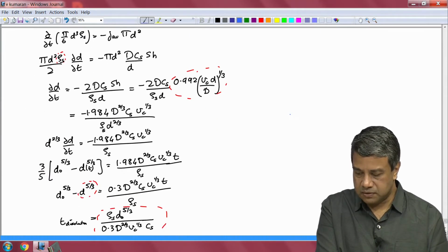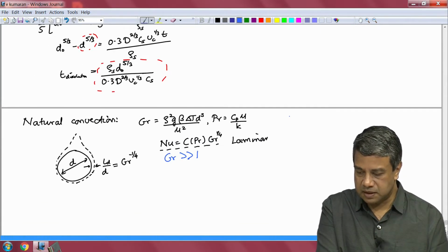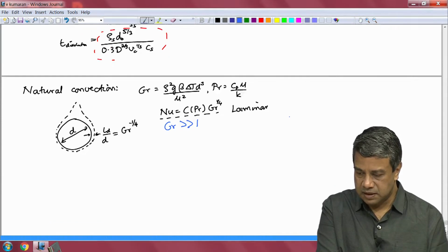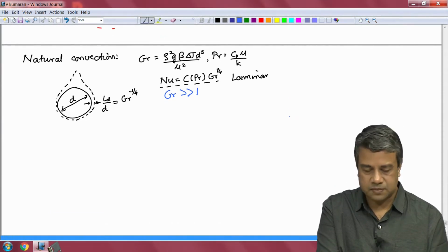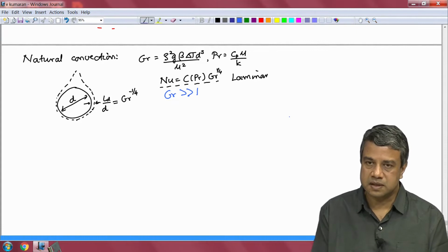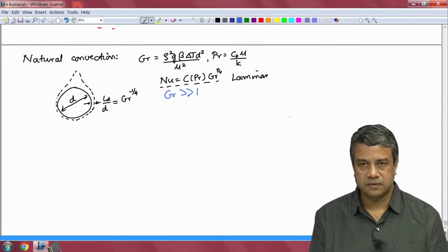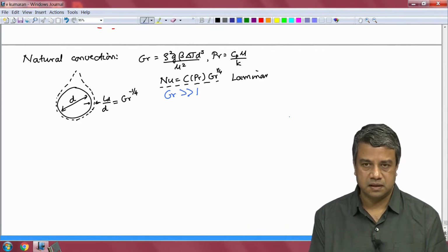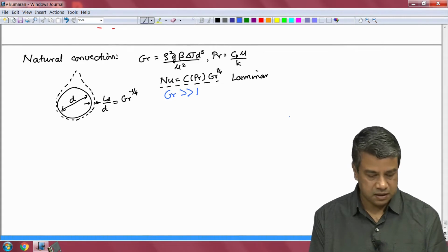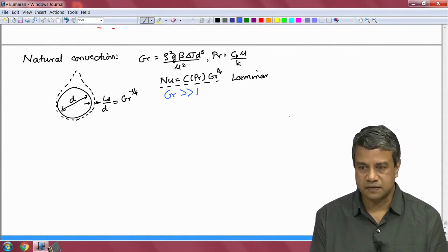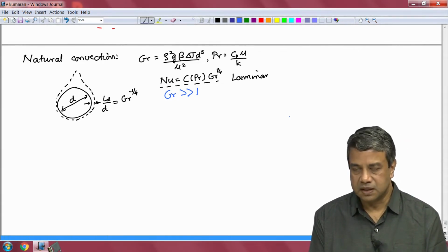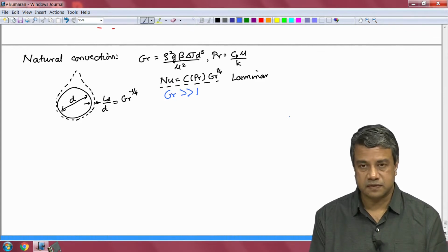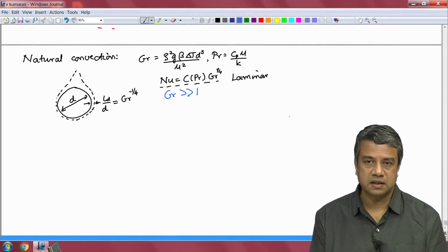So, I had gone through diffusion dominated transport and forced convection where the velocity field is specified, and I was considering natural convection heat transfer. In this particular case, there is a difference because the Grashof number depends on the temperature difference. And we are usually considering the case where the Grashof number is large.